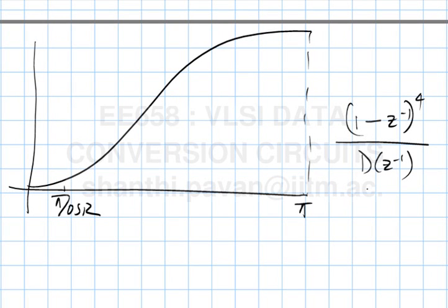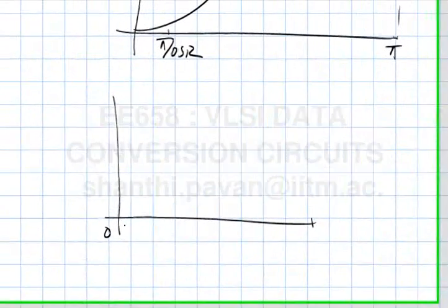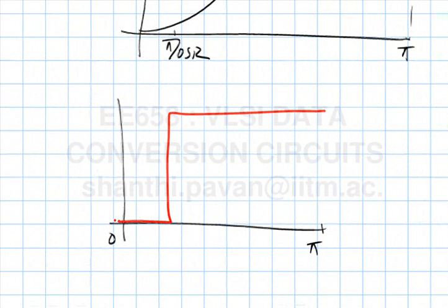And there are many families of high pass filters, and people have figured out ways of computing the coefficients of high pass filters given pass band ripple. This approximation problem has been solved. If you want to approximate this brick wall characteristic, this has got nothing to do with sigma delta modulators, right? So this is nothing but a high pass filter design problem.